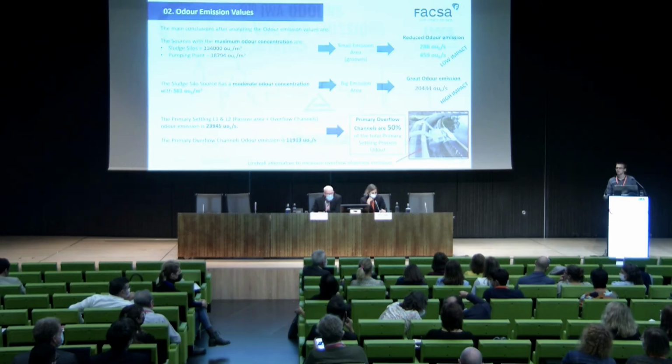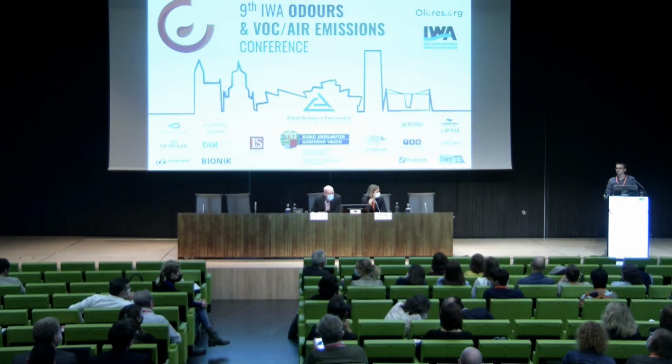No, I mean, what technology do you use to treat the odor in the covered elements? I mean, what did you consider? You cover the stabilization reservoir. Okay, you cover it, but how do you treat the air? We just proposed to cover them. Then we saw what happened if we cover this part or that part, and we saw with our modeling how this reduces the impact that we have. Once we know that this could be interesting to do, we have to think about the technology that we have to use in order to get this into a technical part. So in the case of the homogenization reservoir, it was a problem because it was not possible to cover all of this. That's why this option was just removed. It was not considered.